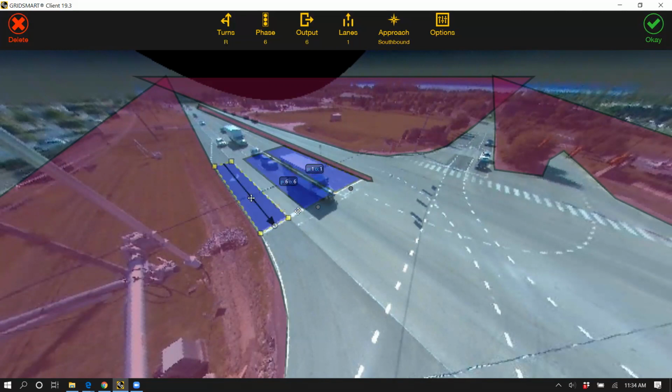So if you got a big, huge snow bank on the side of the road over here, and you can just see the tire tracks are naturally shifting over, you can adjust your zones accordingly. You're going to need to monitor that, though, because if you do make those changes, when the snowbanks disappear, your flow of traffic will be off those zones.